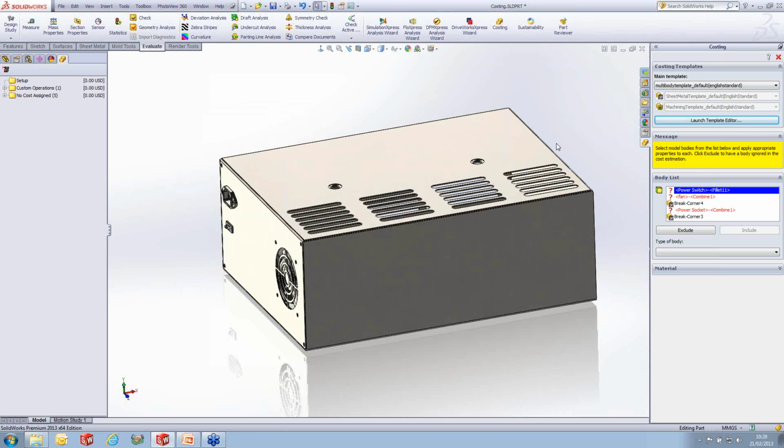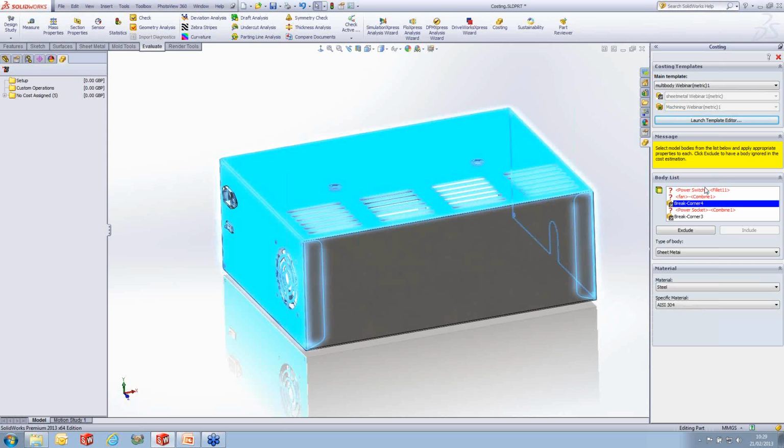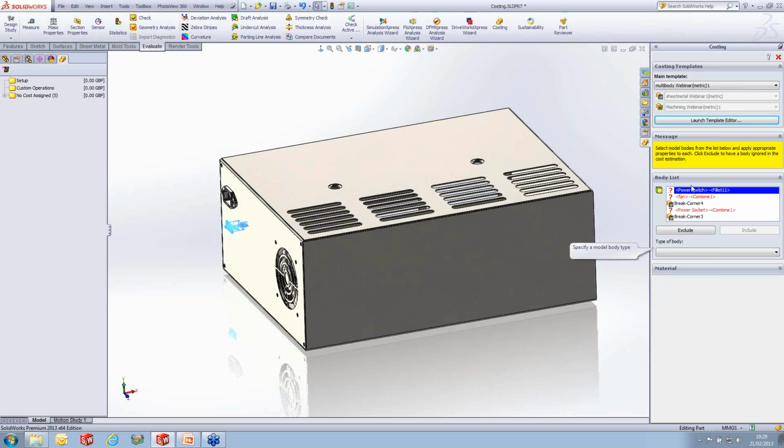Okay, so having created the template, back in this right hand side here, we should have the item available to select from. Okay, and then once we've chosen the item, it should choose for us the 2 templates we want to use. Then what we need to do is go ahead and actually select what these bodies are. So you can see some of them have got question marks next to them. They're the items that are sort of bought in for this particular operation. It hasn't automatically picked one on whether it would be machined or sheet metal parts, because obviously they probably wouldn't be either.